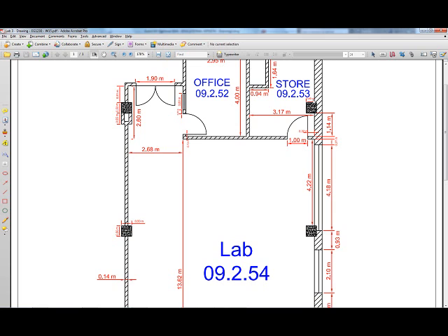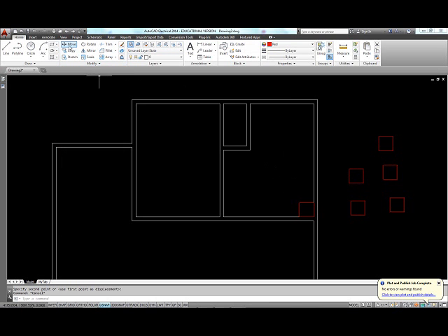See, the dimension from here to the end is 40 with a total width of 50, so the remainder is 10 centimeters or 100 millimeters. So I'm going to say move this object, spacebar from this end, and then at 1140 comma 100, because I want to go up and to the right.